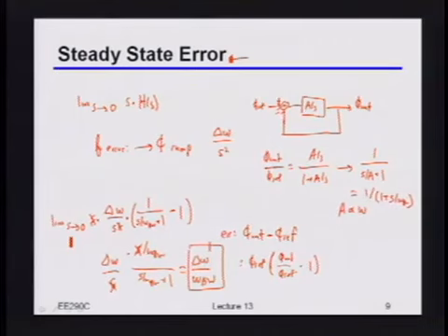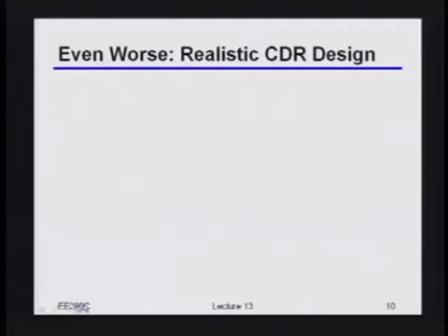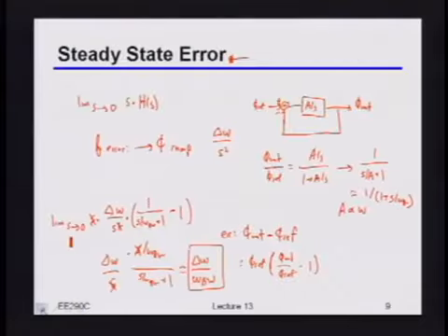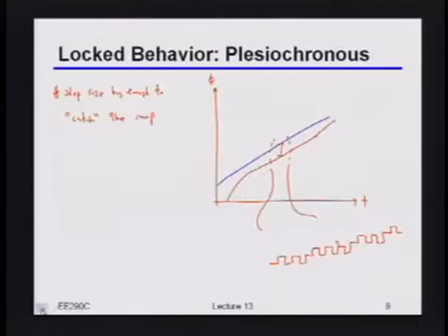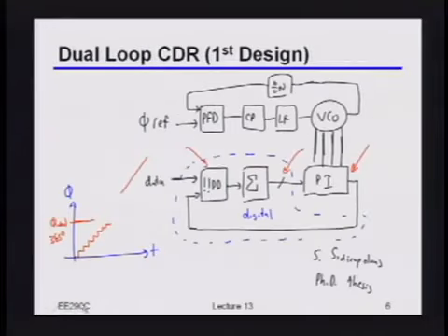Now, one thing that is going to make life a little bit worse is that, as I was mentioning before, those updates are coming at a pretty high rate. If I'm running this thing at, let's say, 12 gigahertz or 12 gigabits, I'm going to be getting these updates at a 12 gigahertz rate, or 12 gigasamples per second. That's probably much faster than I really want. That's probably much more data than I can effectively use, or at least building the digital processing to run at that speed will probably cost me quite a bit of power.